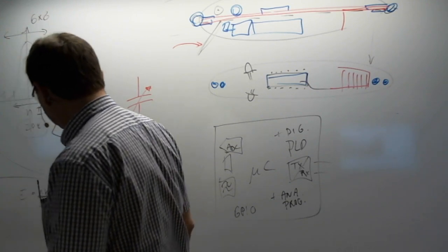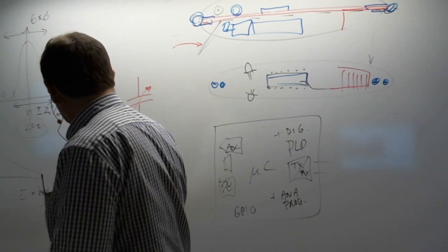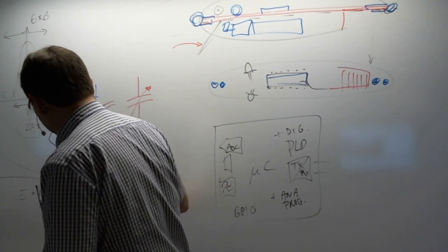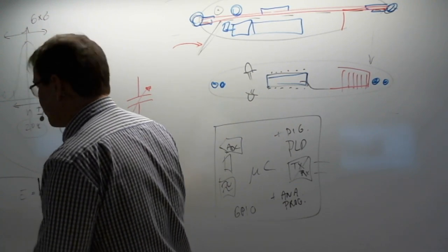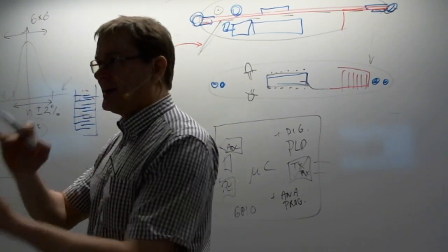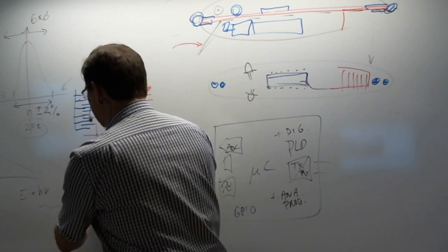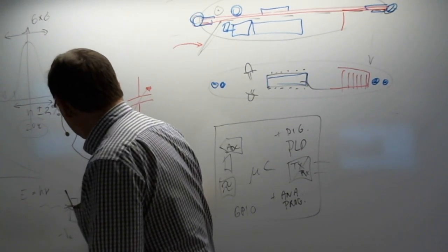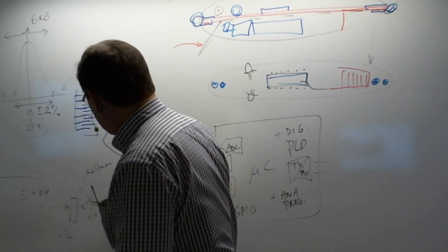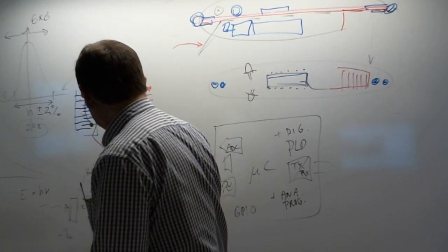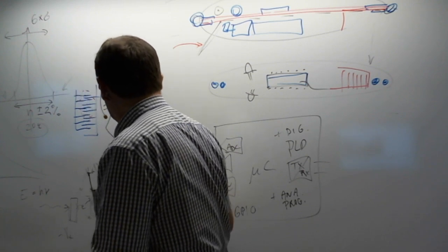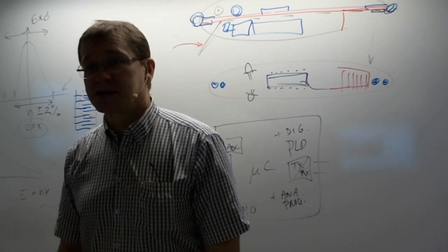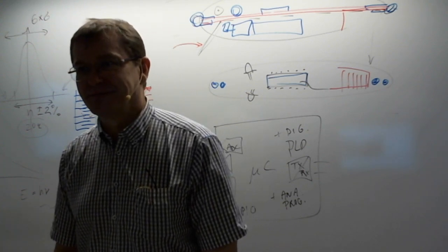You can grab it using this more positive dynode here. It starts traveling there, hits the dynode, and it multiplies. Because you are accelerating the electron, it hits and releases the energy into this material, and then basically you get 2 or more electrons, and then you can have a chain here, an acceleration chain, and finally you have even a microampere pulse of current coming out.